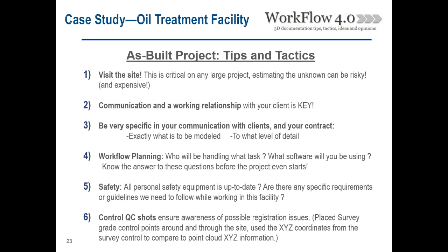On any large project, we see that it's critical to visit the site, because if you get sent a paper, which if you've done scanning for quite a while, you'll know you've gotten one of those projects where somebody sends you a piece of paper with some lines on it and says they need a couple things scanned, and then you get to the site and it's an entire couple weeks worth of scanning. So before you do any estimating or proposals or anything official, if it's a large project, you want to visit the site so you can really get a feel for what is the level of detail. How long is it going to take?